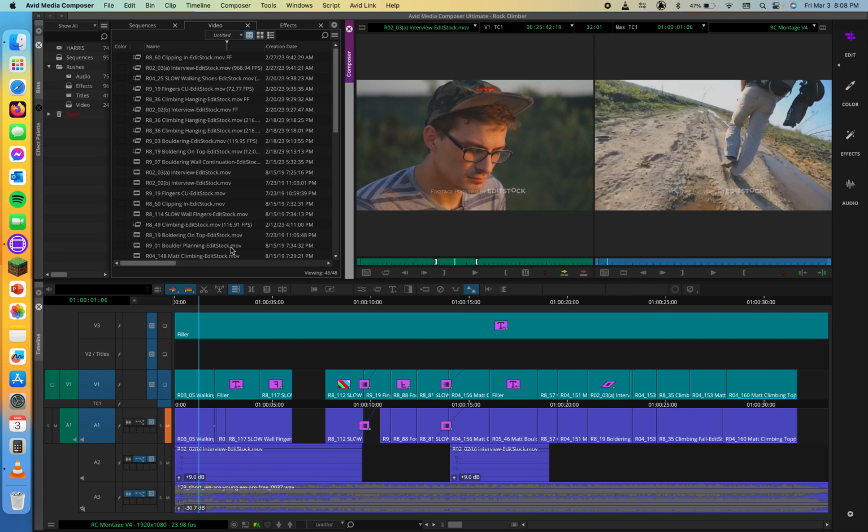All right, so that's enough of that. Let's move now to bin creation and naming strategies. So as you've experienced, a new project includes one bin that's named after the project itself. During MC110, you started to organize a new project by renaming the default bins and creating additional ones. Let's take this a step further by considering the following bin creation and naming strategies. So, depending on your project scope, you may need many bins. As you decide what bins to create and how many of them, and how you're going to name them, consider your project's workflow and how the bins you create can serve that workflow.